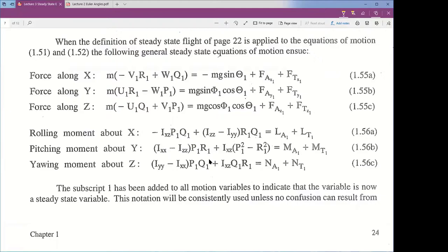We're seeing, can we have lift equals weight, thrust equals drag, and if we're in a turn, it becomes more complicated than that. So there's a lot we can do with this. And we've done some of that in 514. We're going to analyze a few more lateral directional cases. We'll look at a one engine inoperative condition in a twin engine aircraft where you have to deflect rudder to trim the airplane to keep it from yawing. So we'll analyze that. We'll look at the full 3x3 lateral directional trim problem.